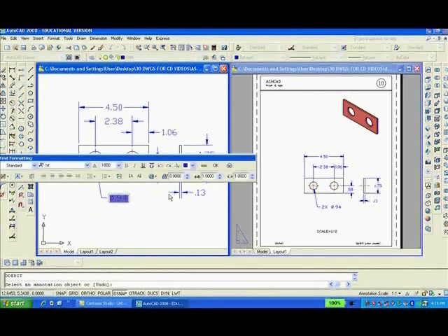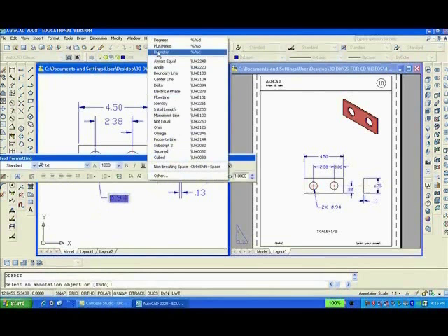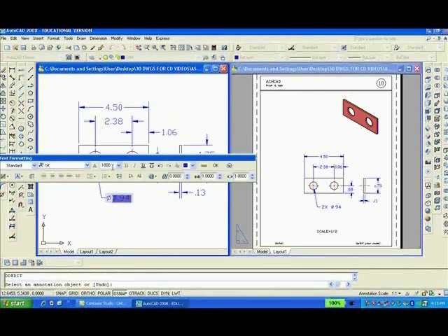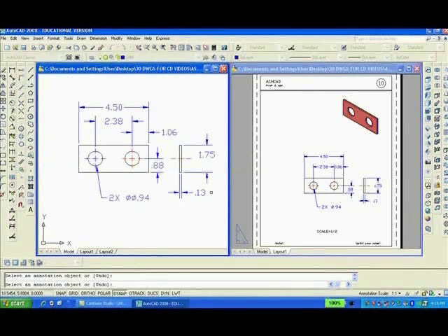M view comes up, I can click on the symbol and put a diameter. I can put a diameter, and I can even click before that if I want, and backspace. I'll put 2x space and click OK. The 2D drawing is complete, so now we want to make the solid.